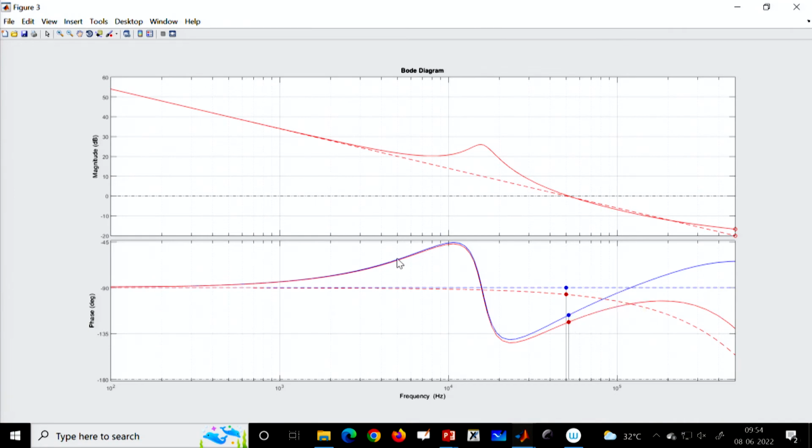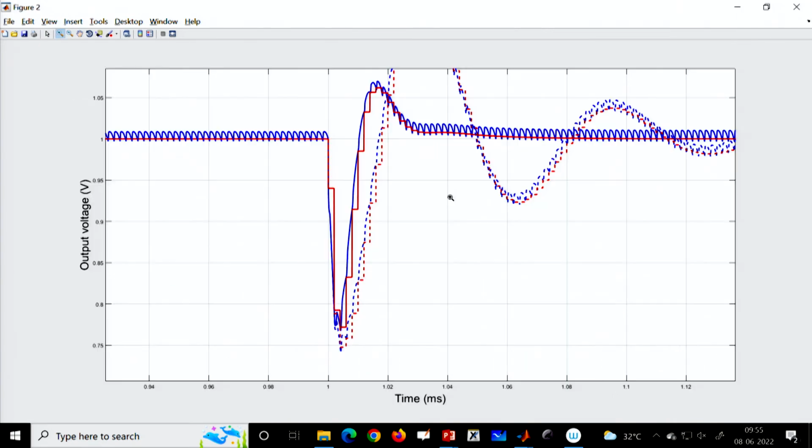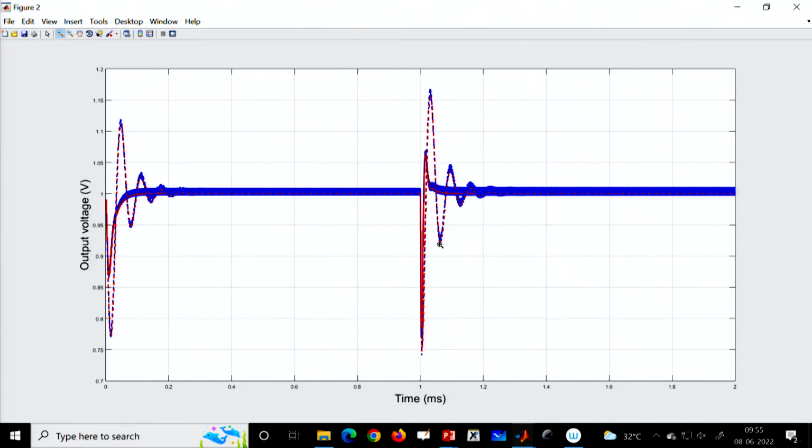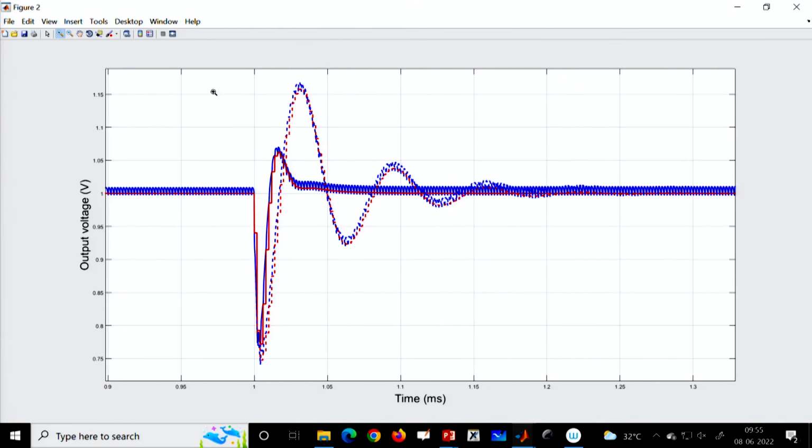And you can see, since we are not doing any exact cancellation, there can be an LC pole effect. That means there is a phase swing, and the amplitude also has a peaking effect. Now we want to compare what our transient response is. So we want to see the transient response, and if you compare it, you can see that